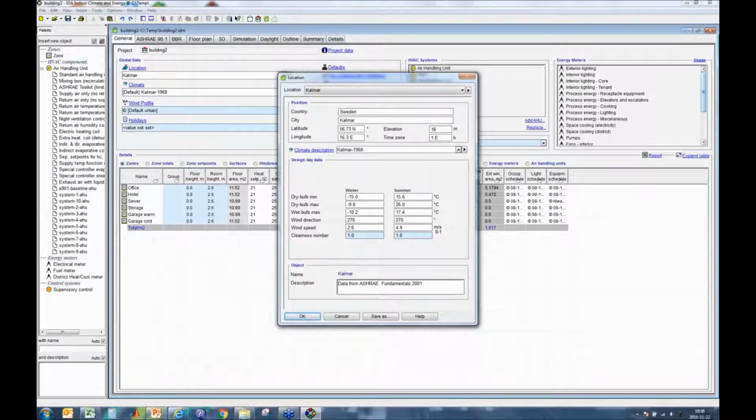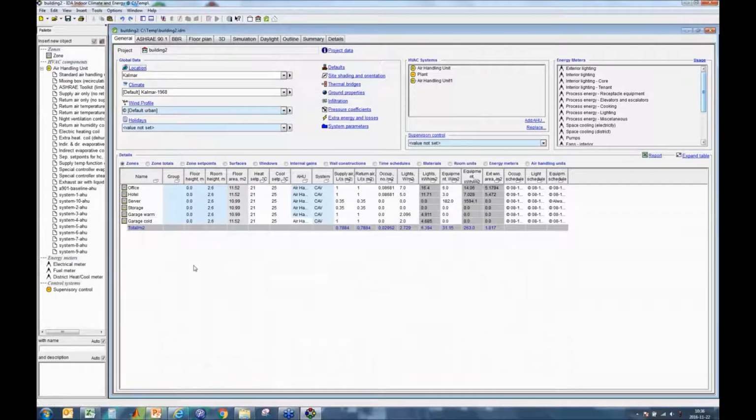One question from Vin Huyn, asking, the baseline heating and cooling capacities are auto-sized based on proposed capacities. Should you then run the heating and cooling demand simulation for the proposed first before running the baseline for orientation simulations? Well, that's not really true. You design and size the proposed case separately using the model you built.